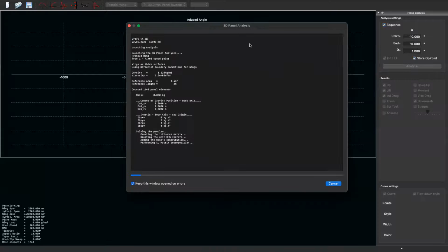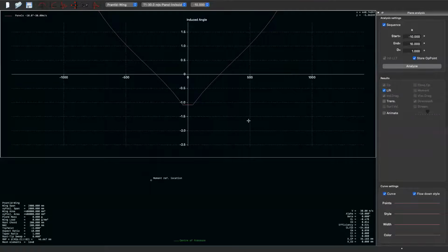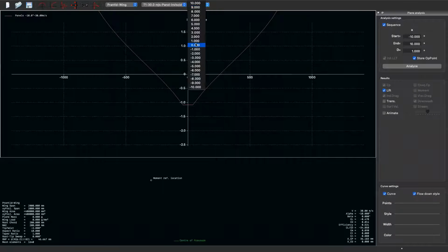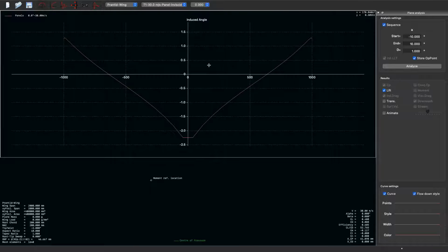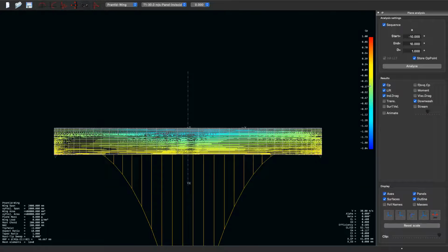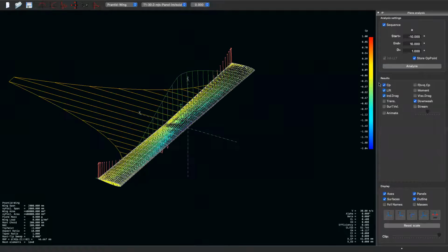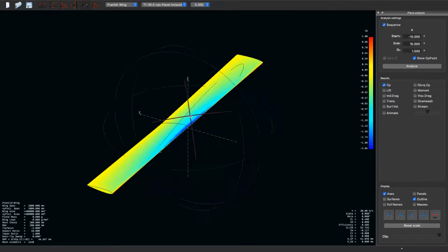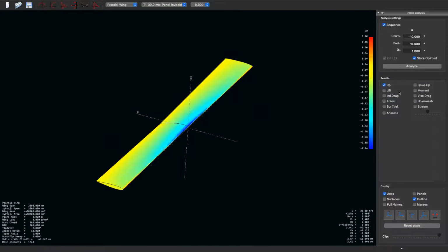Click Analyze. Right. Now, this may take some time, right? So the more panels you have, the higher the computational time will be. All right. So you can see that, in this case, in 3D panels, most of the angles of attack are converged, right? Which is, again, pretty cool. However, one really interesting aspect of the 3D panel analysis is that it will give you a CP distribution on the wing, right? I'm going to uncheck the lift, induced drag and all that. Look at that. That's my CP distribution. Now, you all should know by now what a CP, coefficient of pressure, is, right?